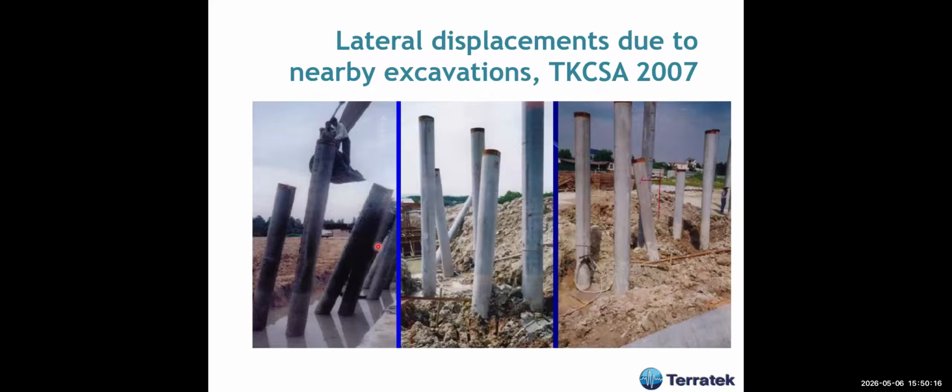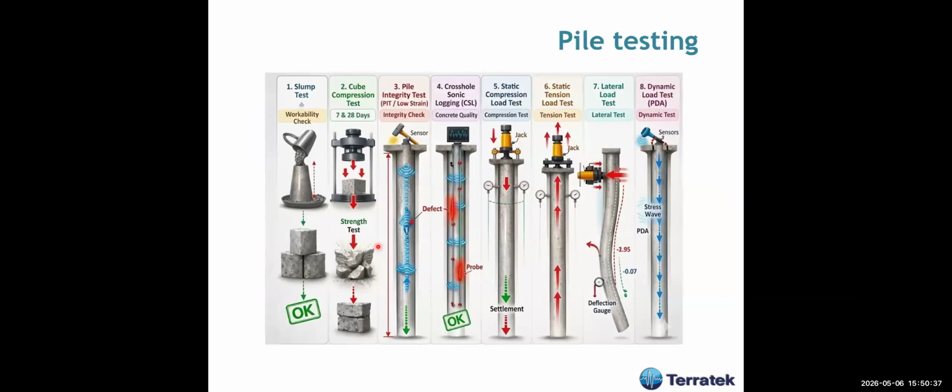Okay? So my recommendation is that for all these pile blocks, they have to have a proper excavation design in order to avoid horizontal displacement of the soil close to the piles.